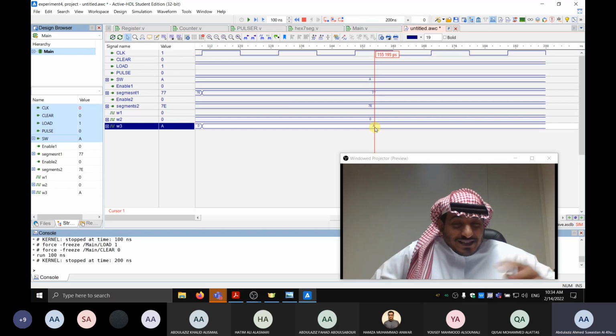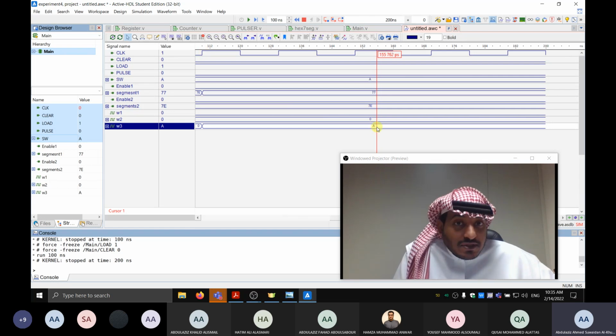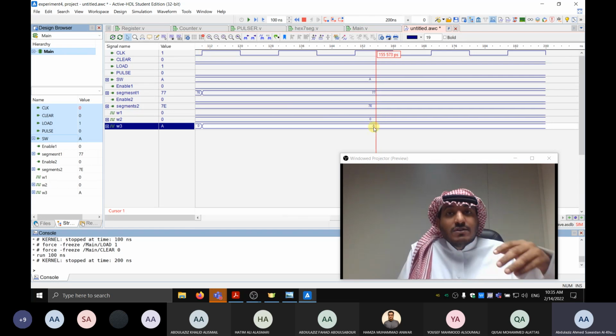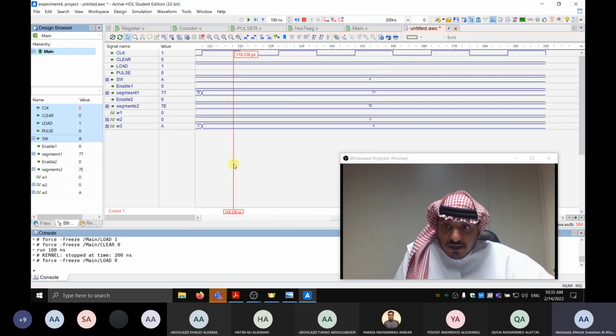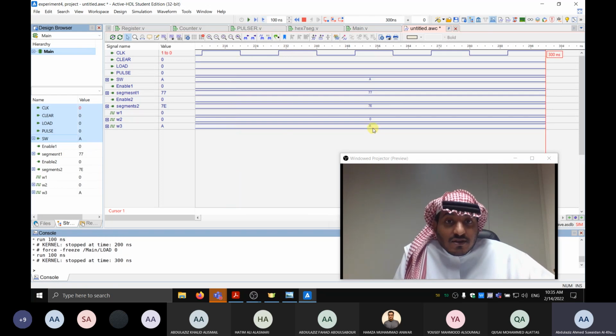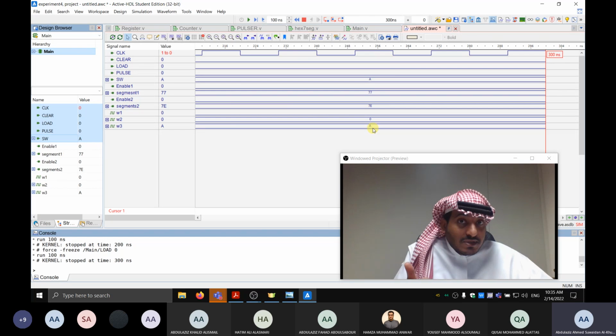Did you understand? It's step by step. You prepare the buttons and then you say run for. So now after I press the button, at the next positive edge, the load worked. Now see the load is A. So the memory has been written by A. Okay. Now I will remove the load L and run again. Of course, it should be the same value, A. Nothing happens. Even if you change the switches, it's supposed to be the same thing.